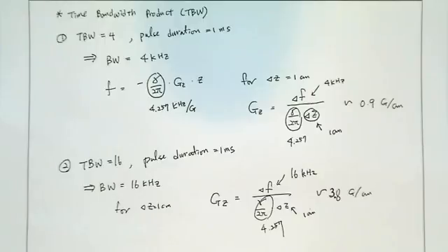So for a given pulse duration that you can allow for a given hardware limitation, like gradient amplitude and B1 amplitude, you can maximize your time bandwidth product to have a better slice profile. Okay? So that's the way that you think about how to design the RF pulse, just simply looking at the numbers only. We're not talking about the shape, just determining the proper time bandwidth product and proper pulse duration can improve a lot of the MR imaging quality because of a better slice profile for a given restriction.